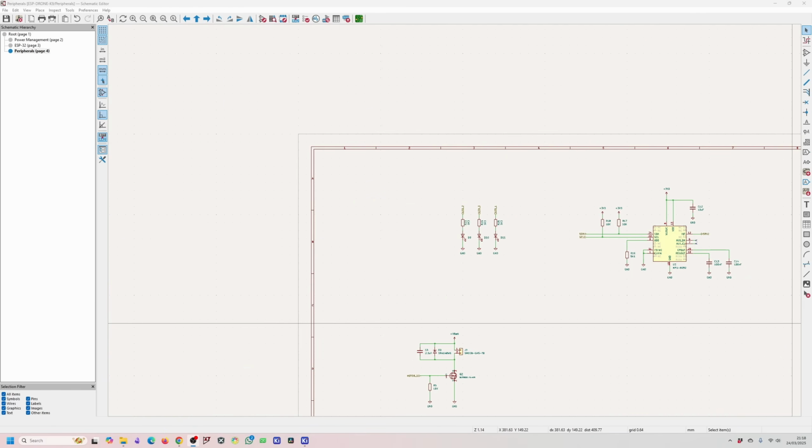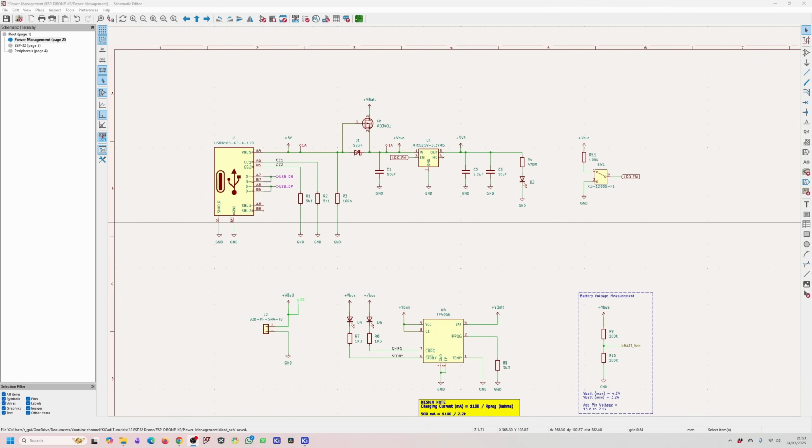In this video, I'm going to look at net classes in a lot more detail, and I'll show you how that influences the PCB design as well. Let's quickly talk about why using net classes for PCB design is important. Net classes allow you to categorize different types of signals in your PCB design to allow you to apply specific rules to them. Instead of manually adjusting the width, the clearance, or wire sizes for each net for the PCB design, you can define a set of rules for an entire group of related signals.